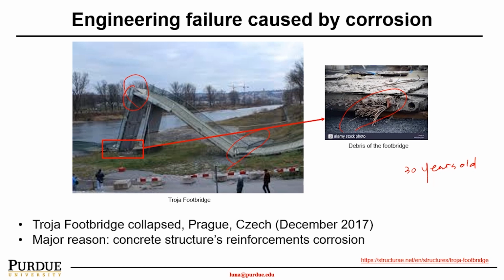What we really need to learn from this lesson is that you need to understand what is to be measured, right? In this case, the corrosion is such a significant contributor, and what we're looking at is deflection. So again, the knowledge of the NDE is very important, right? The inspector's knowledge, where to measure, what to measure, what you're looking for is very important. It's not only about what type of tools or methods you're using. So that's one of the take-home messages from this particular accident I would like to point out.